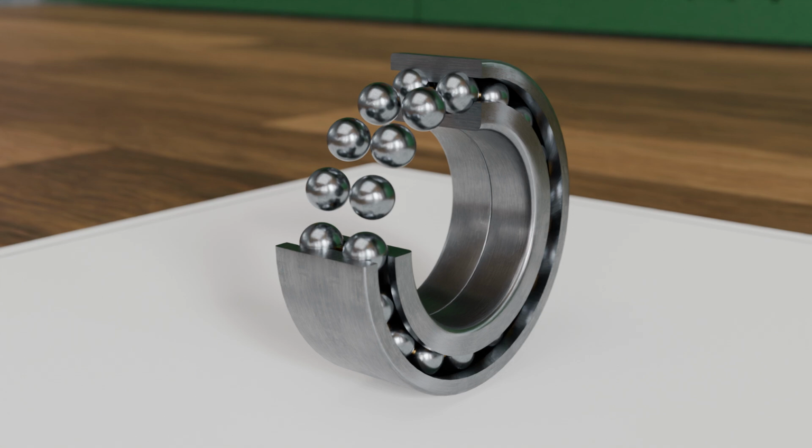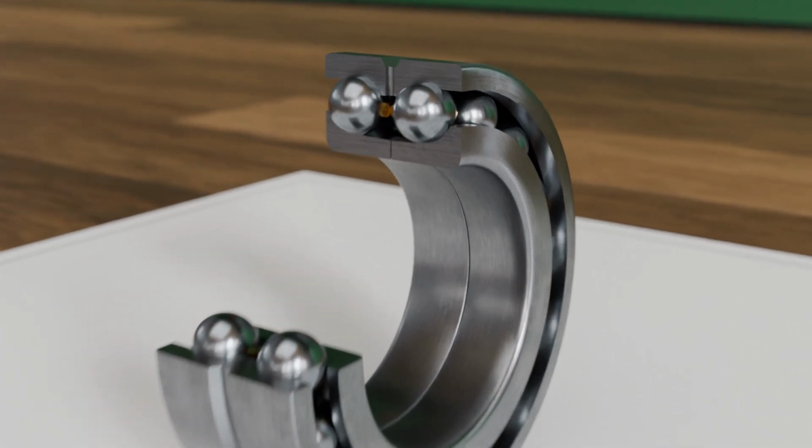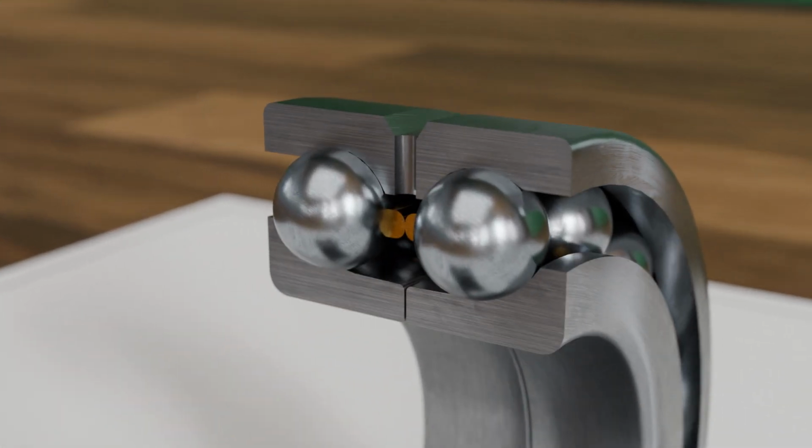For easy maintenance, lubrication holes and a continuous lubrication groove can additionally be provided in the outer ring to facilitate relubrication. The continuous groove has the advantage that the lubrication hole in the bearing does not have to align precisely with a lubrication hole in the housing. Furthermore, multiple lubrication points can be implemented on the housing, through which the grease is injected. The grease then distributes evenly via the lubrication groove to the lubrication holes, ensuring reliable delivery to the rolling elements.